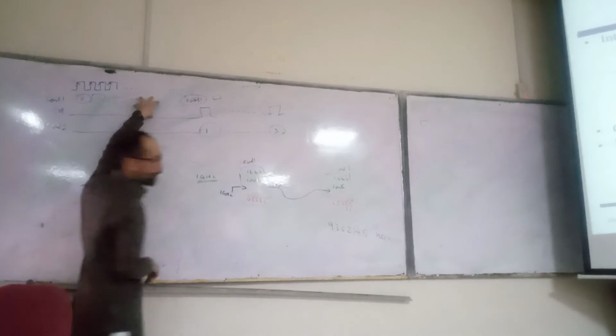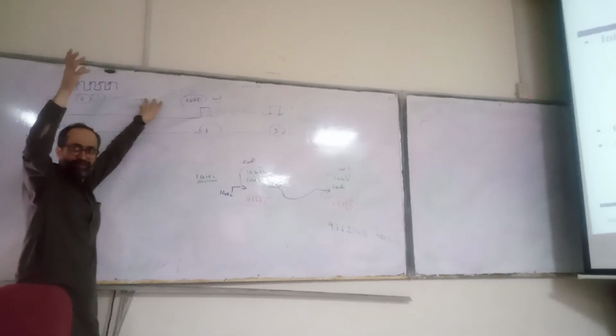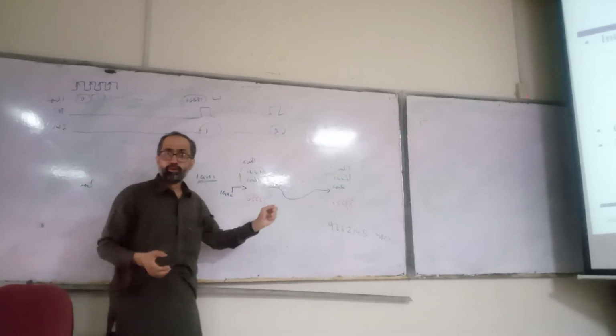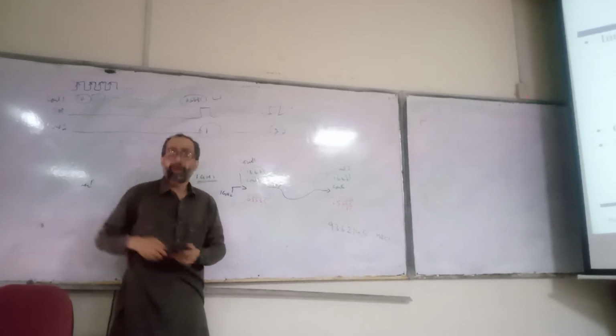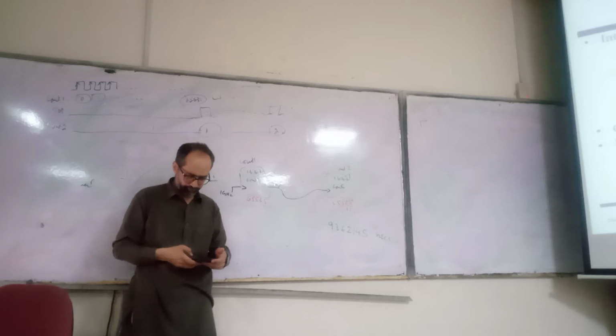Just assume this is the seconds. When it reaches its maximum value, 65,535, it will wrap around to 0, and the top signal will be 1. This signal is then given to the next counter, like the minutes.